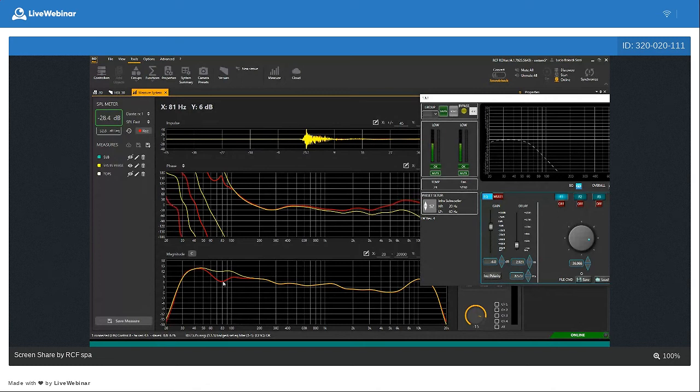It means that if we are working with an amplifier of 2000 watts, we are using just 700 watts in this case, because of the cancellation due to the fact that we are not in phase in the crossover region. So it is definitely very important to deal with phase alignment.